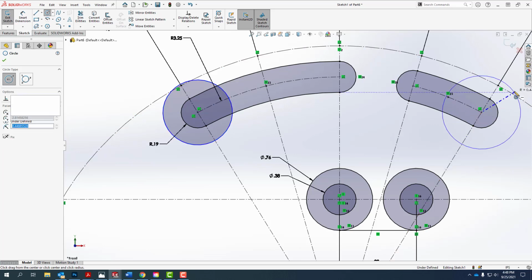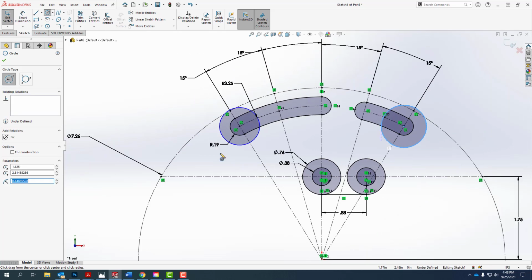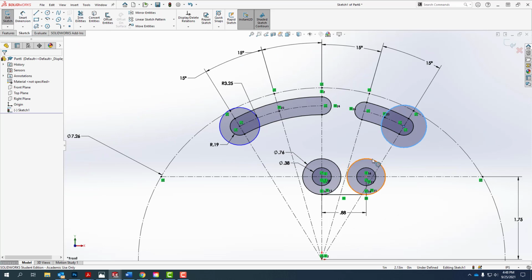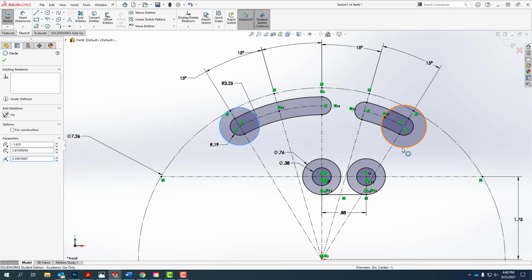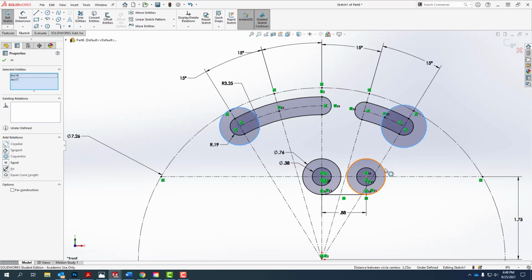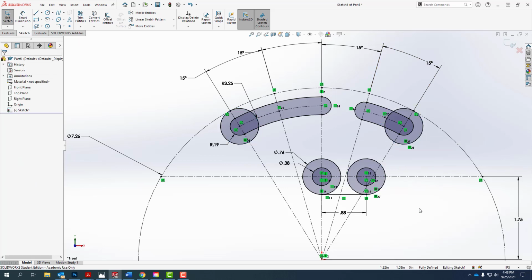and a circle around this one. And these two circles should be equal to these, because again that call out is 7 by radius 38. So this gives me 1, 2, 3, 4 of those radiuses. So I'll select here, I'll select here, and select here, all while holding down my control key. Let go of the control key and set those to being equal to each other.